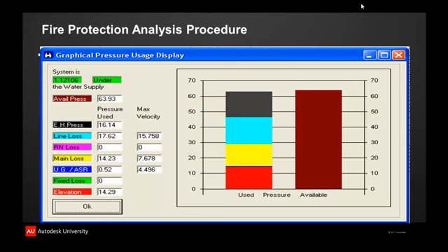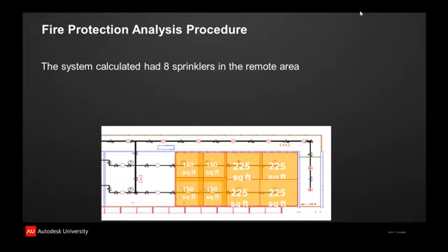By summarizing it this way, it helps bring into focus the idea that it's those three components: the out, the up, and the through. The brown bar on this chart on the right is the pressure available out in the street, and we always want the left bar to be shorter by some amount than the bar on the right, so that what we need is less than what we have available.